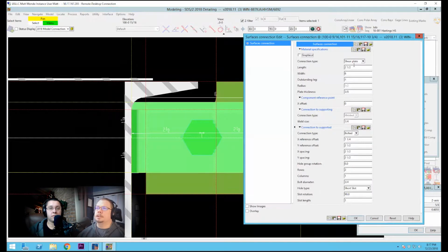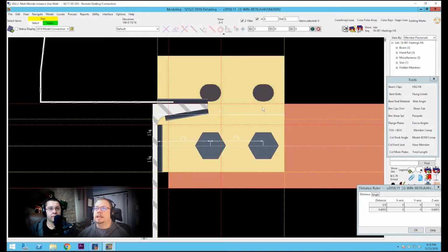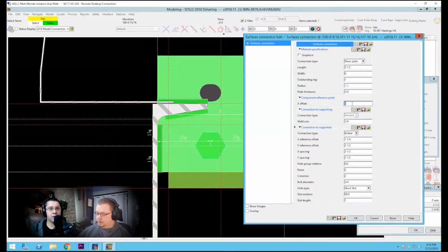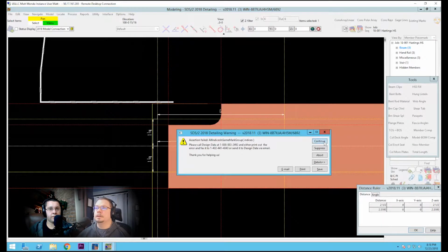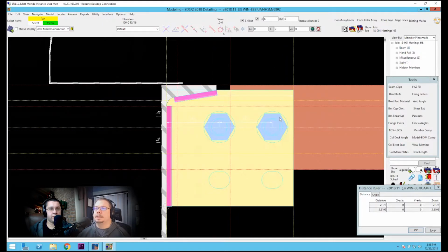All right, now just to show you, and this is going to run off the beam a little bit, but let's say we go to a 5.5, and I'm going to leave everything pretty much the way it is just to see what this does. We'll go 2 columns so you can see how this is going to give us the 4 bolts. And you can see how that reacts. So then again, once we get that set up the way we want it within the material, we want to use that X offset to bring this down to where we really want it to be. Which I should have known that was going to be 2.5, so bring that down. Probably not a big fan of the fact that that's running right off the bottom of the material. But you see that does in fact work.